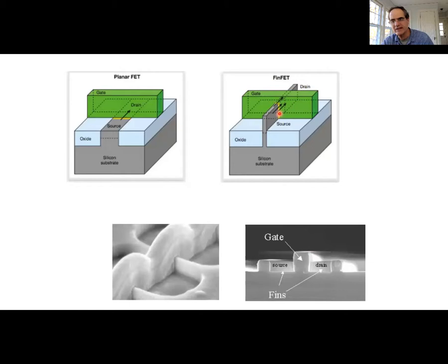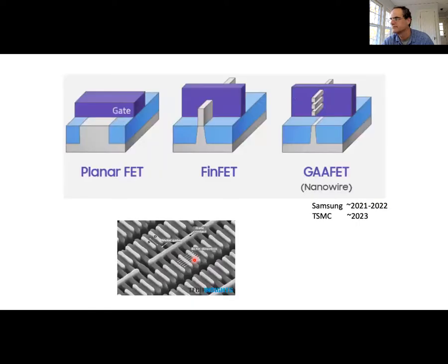And it really suppresses things like tunneling. Okay, here's an electron microscope image of a FinFET. Here's the fin, and here's the gate electrode that almost completely surrounds it.